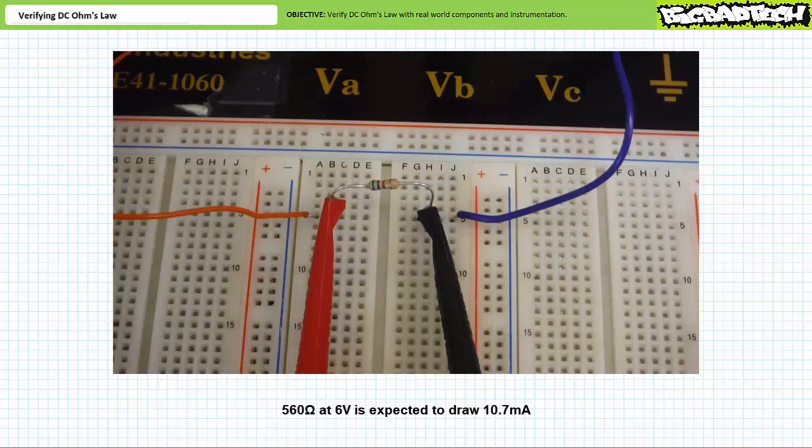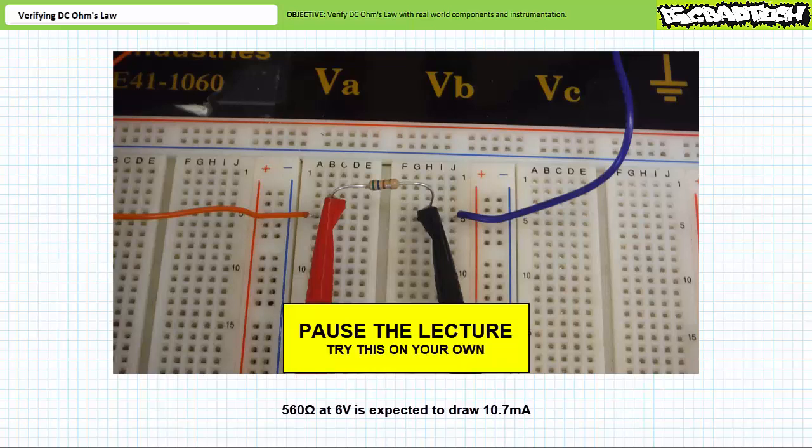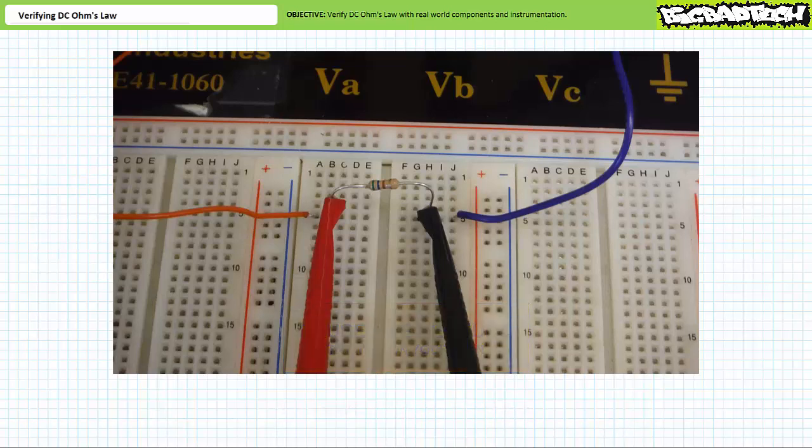Take a look at this and tell me if they've installed the ammeter correctly, and see if you can predict what might happen if they turn the power supply on. By all means, pause the lecture and try this on your own. What's wrong? If you're tracking, you should have come to the following conclusion. This is not how you install an ammeter. You recall that ammeters must be placed in series or in line with elements of interest, such that all current passes through the ammeter. Placement of an ammeter in parallel with an element of interest can have disastrous consequences. Recall that ideal ammeters are modeled as 0 ohm resistances through which substantial current can flow.